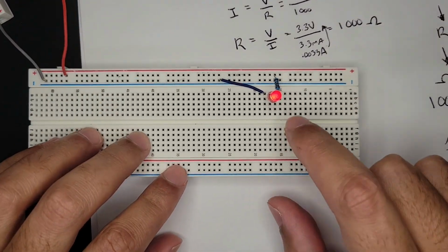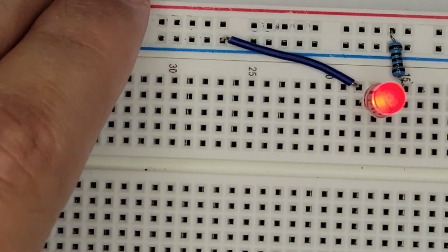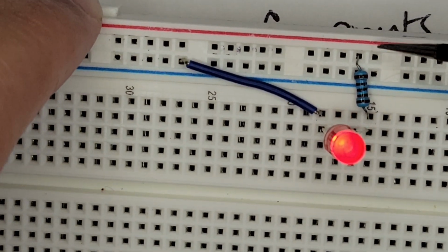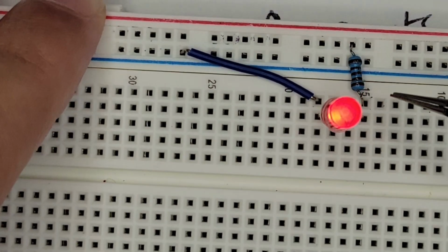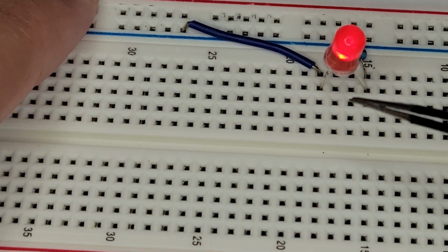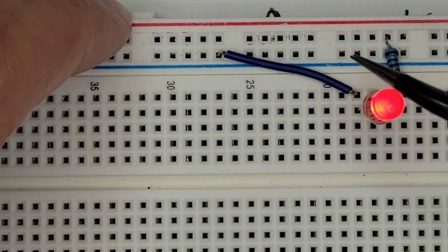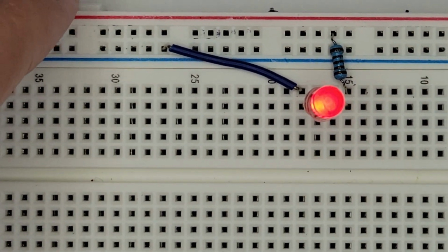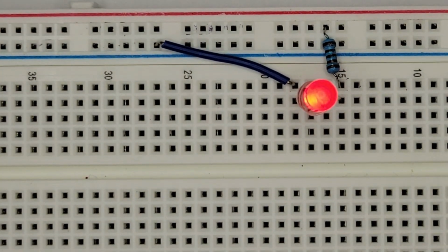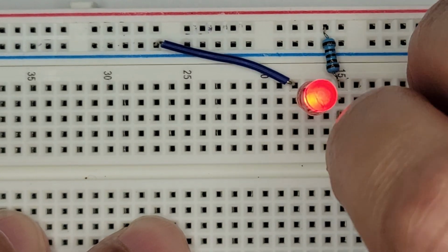is, let's say we had this circuit right here, right? We have, let me zoom in again, sorry. All the zooming in and out. So we have power, again, coming from the resistor, limiting the current to 3.3 milliamps. And the LED is on because it's connected to ground. So we have a full circuit here. Now, what would happen if we connected another wire to where the LED is getting power from the resistor?